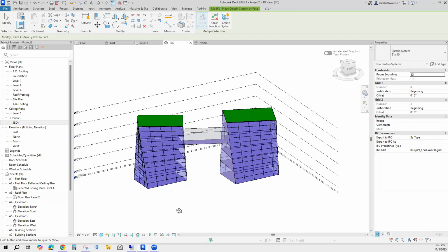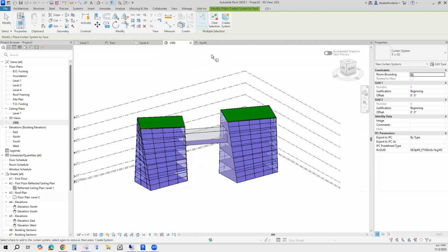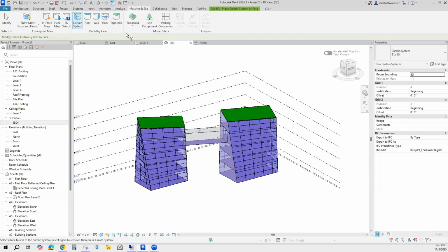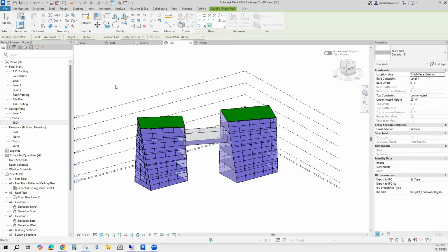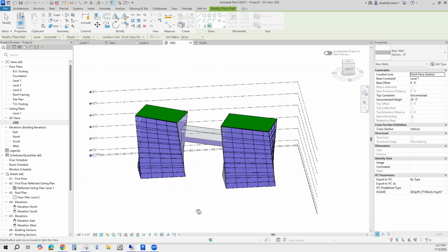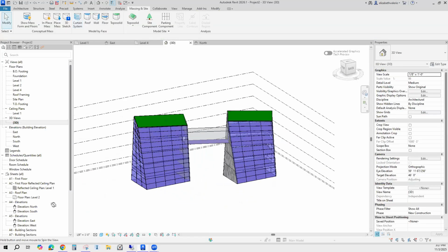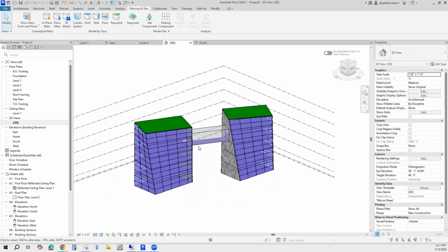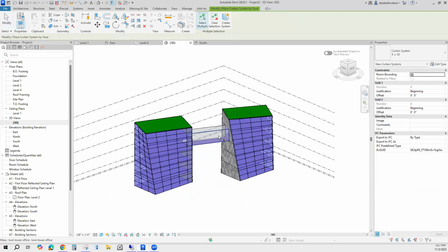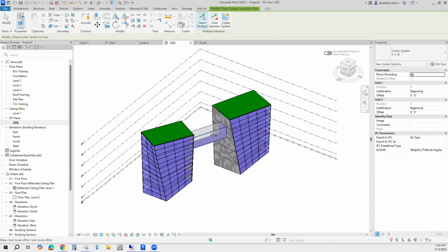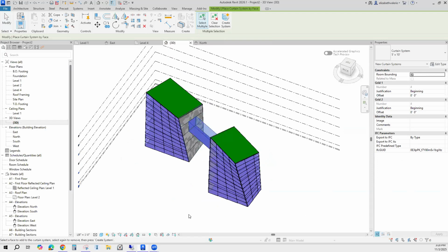On the 2 walls that face each other, I'm going to create solid walls. So I'm going to go to Massing & Site, wall from face, select this wall and this wall. So those are solid. And then for the walkway, I want a curtain wall system on the exterior and on the top. So I'm going to do curtain system, create system, enter. There we go.